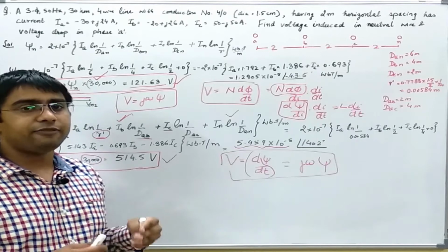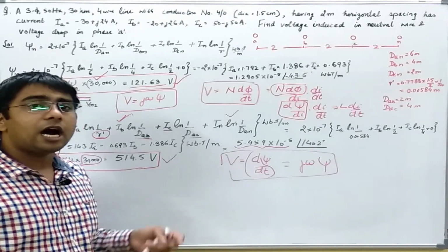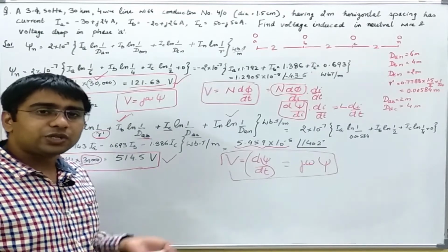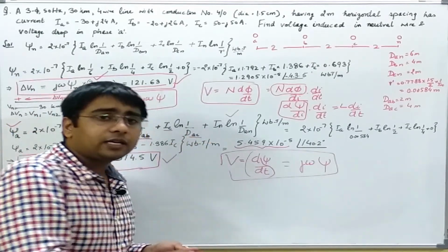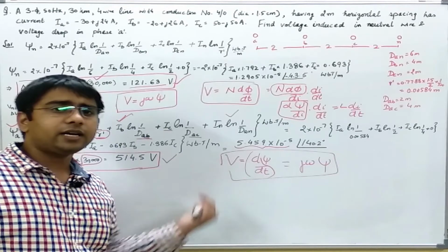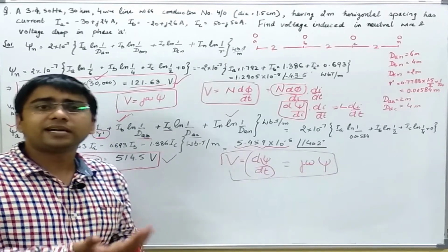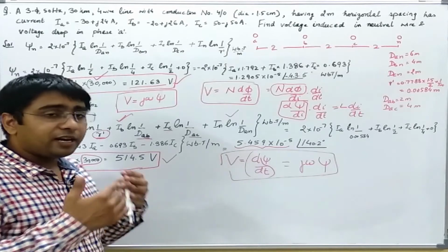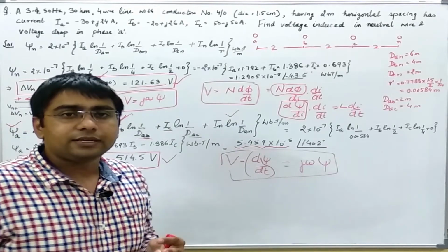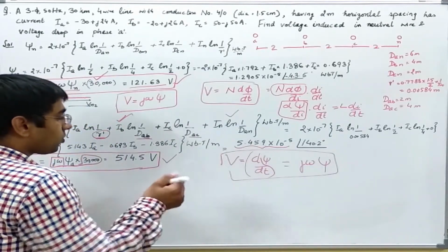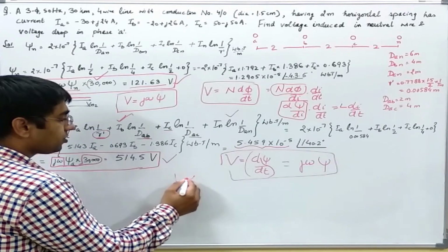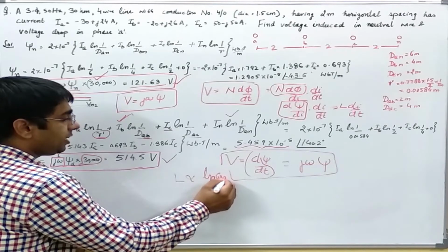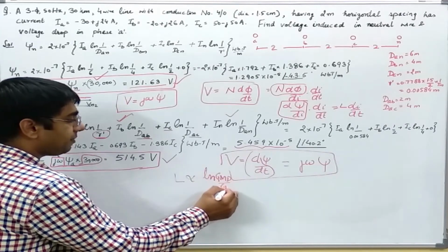So we will study in later chapters how to reduce this voltage drop, various measures to reduce the inductance of the conductor also, which we already studied here also, that we use bundled conductors, multi-circuit lines, so that the geometric mean radius increases, since L is proportional to natural log GMD upon GMR.